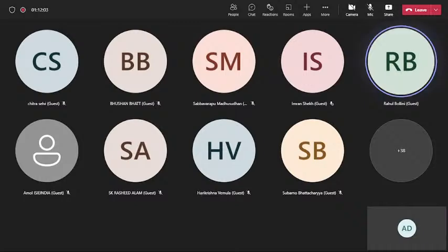Suppose the battery is rated at 30 Ah. There are low speed scooters using 15 amps and the big high speed scooters using 30 amps and all that. But if you want to just accelerate all the time, you're just heating up the battery. So there are two things: either the battery will cut off on the field, or if your BMS is not good enough, simply batteries will get heated up and over temperature cut off doesn't happen.